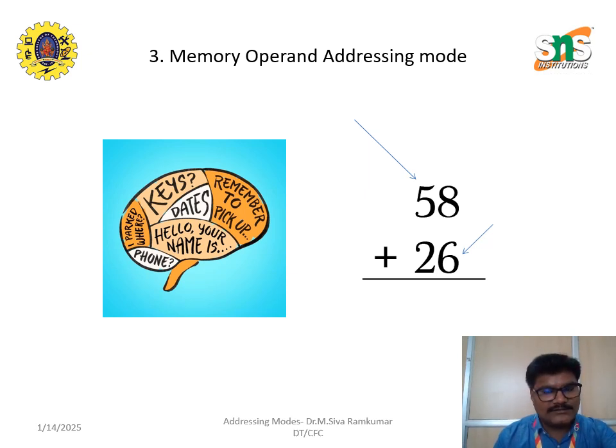Here we are moving to the memory operand addressing mode, where the operand is located in memory, with the memory address specified directly in the instruction. It's like having a specific shelf number in the library to find your book. For example, MOVWF 0x20 moves the value from WREG to the memory location 0x20. This is great when you need to access a specific memory location or register. What real world examples might require this precision memory handling?